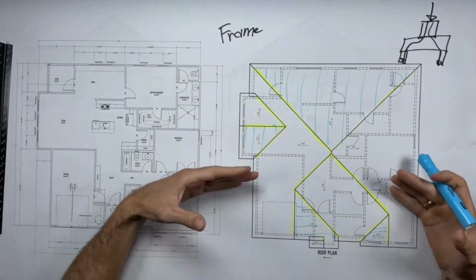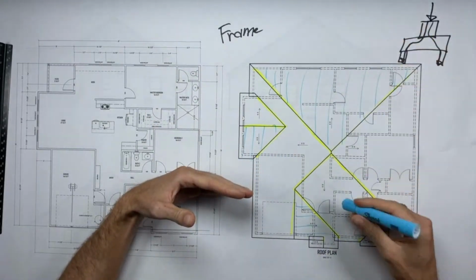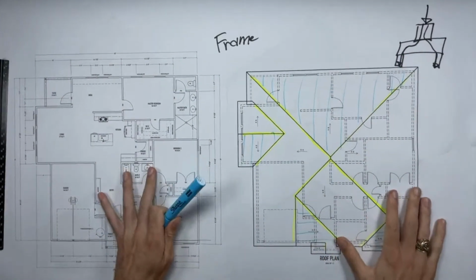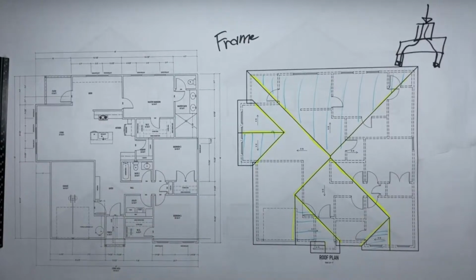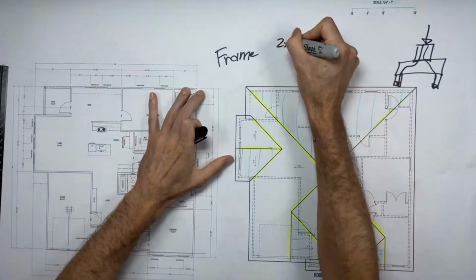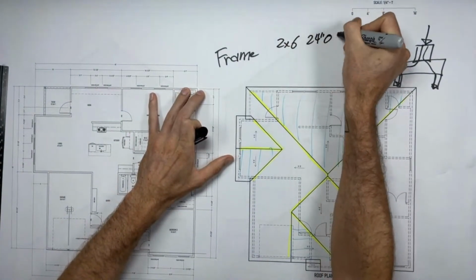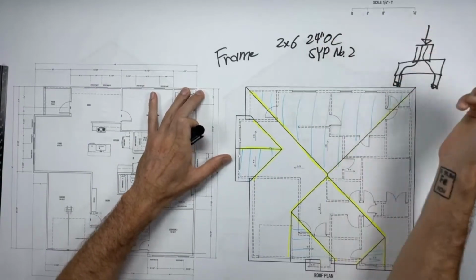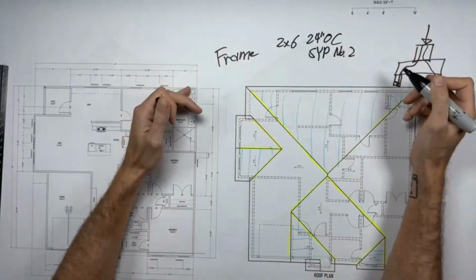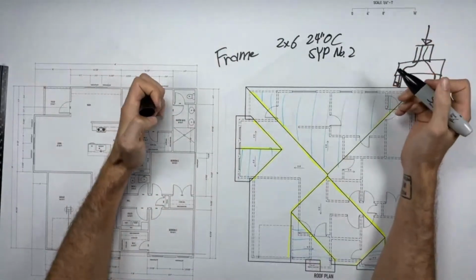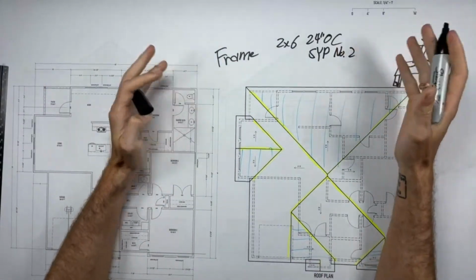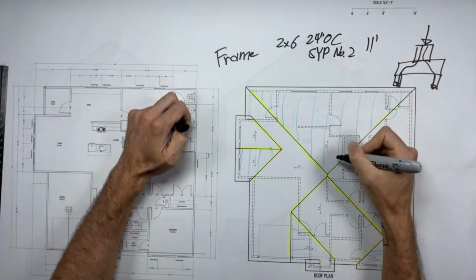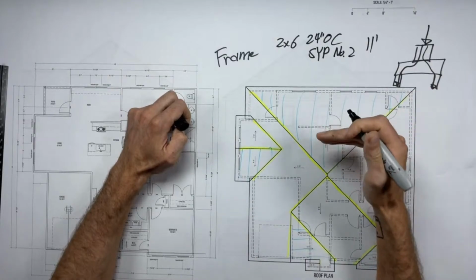So we're going to pretend they're all there. And we want to think about how far our rafters can run horizontally on our plan before needing to be supported. Well, the rule for that is, we're going to assume a few things. We're going to assume that we're going to use 2x6s, 24 inches on center, and we're going to use Southern Yellow Pine grade number 2. Those are the numbers I'm going to use because that's just a very common material. I build in Texas. This is what we use a lot in Texas. It's fairly safe to use. So we can go about 11 feet horizontally in our plan before we have to add support to a member.